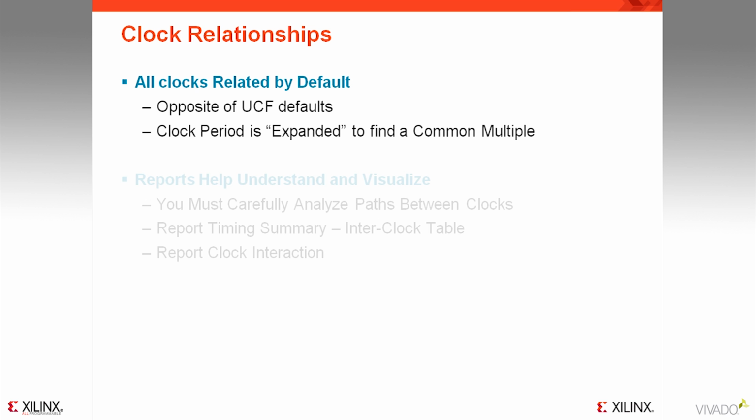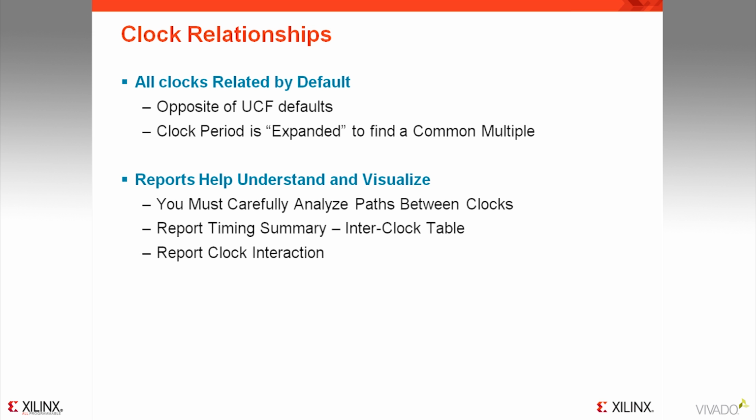You can see that it is critical to carefully analyze paths between clock domains, and Vivado provides reports for this. There are tables of paths in the timing report summary that report the worst paths, if any, found between clock domains, and there is a graphical clock interaction report to help you visualize these paths as well.